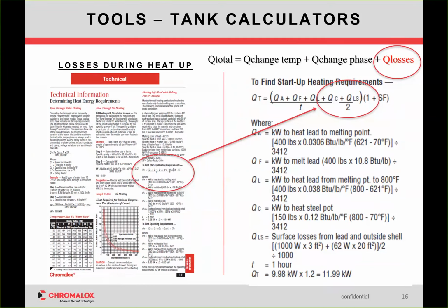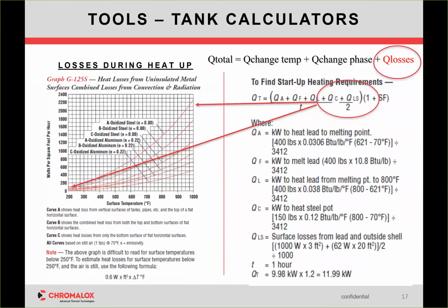Well, when you're heating something in a heat up application, there's a start temperature and an end temperature. In a maintain application, there's not. You're maintaining a temperature, so that loss is constant. You're at the high temperature already because you're not raising the temperature. So it's important to differentiate between the two if we're maintaining or heating a product. If you're heating a product, you got a start temperature, so your heat loss is X, but at your end temperature, when you finally heat the tank, it's at Y. The difference between those two is essentially what you want to use as your heat loss, because it can be extreme.